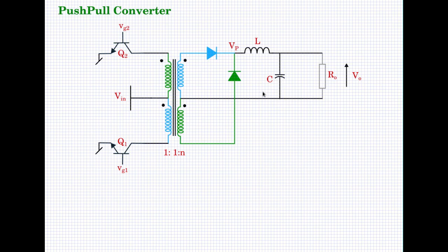into the output capacitors and R0. Now when the switch Q1 is off, let us say for some time both Q1 and Q2 are off. During that time there will be a freewheeling of the inductor, and it will freewheel through this, or it could also freewheel in this path as we are seeing. And then after some time, let us say we are switching on Q2.